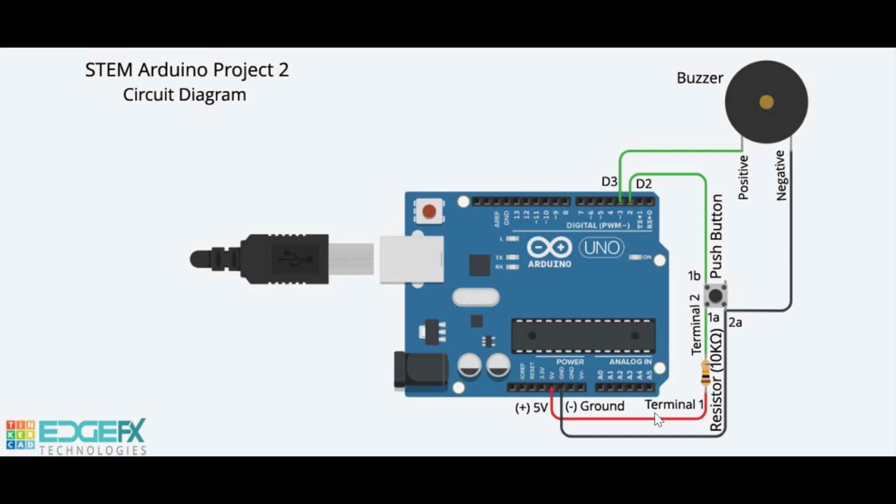The buzzer positive pin is connected to the pin of the Arduino Nano, and its negative pin is connected to ground. The program is written in such a way that when you press the push-button switch, the electric current flows from the positive 5-volt through the push-button switch and lastly to the GND in closed path 1, and the input pin changes the state to logic low.